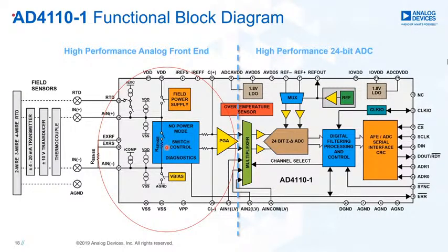Once you feed some signal, you will configure this portion accordingly through the software to accept, handle and manipulate those signals. The second part of the chip is a high performance 24-bit ADC with very good and flexible digital filtering. The digital filter offers you noise-free bits up to 20 at the highest data rate, and you have different options like sinc2, sinc3, sinc1 plus sinc5. It also comes with an internal reference to meet all your accuracy levels.